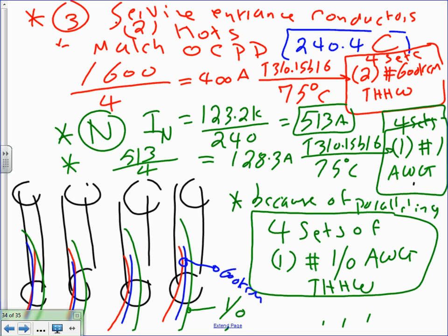That's why we don't size the fuse, 240.6 and all this good stuff. If I understood you right. Any comments, guys? Did I understand you right, Aaron? We were doing it grounded before, but this is the neutral, not necessarily grounded. Sorry. Yeah, 250.122 is for the equipment grounding conductor. This one is for the grounded conductor.